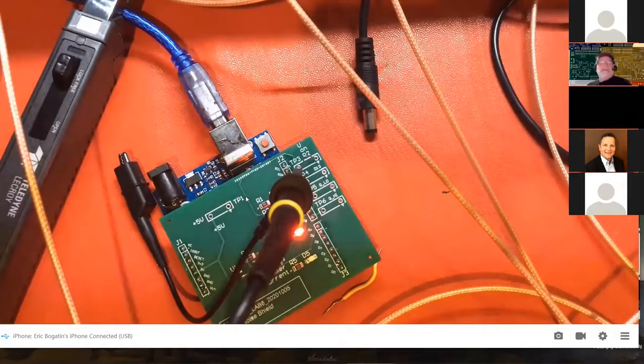The 10x probe is one of those, and generally, if you have a system composed of the probe, the scope, and of course the device that you're looking at, depending on the bandwidth in your device, you would like your probe and scope system to have a bandwidth at least twice the bandwidth of the signal that you're trying to measure.